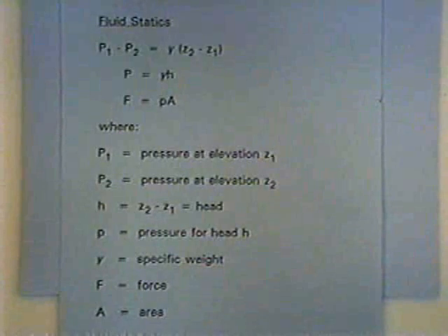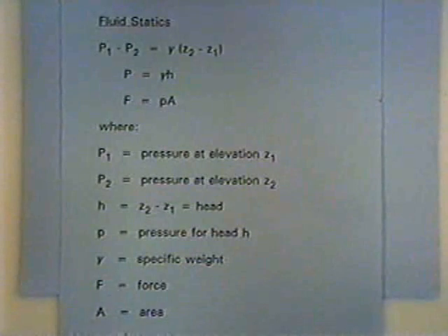Now in fluid statics, we're talking about fluid at rest, no velocity, no movement. And so for a fluid at rest, if you pick a point in the fluid, the pressure is the same in all directions. Viscosity is totally irrelevant. Viscosity doesn't come into play at all. And if you look at a horizontal plane through the fluid, at any point in a horizontal plane, the pressures are going to be the same. And even when we move into fluid dynamics, we often assume, for certain analysis, hydrostatic pressure distribution.